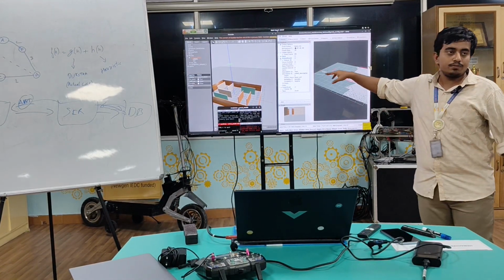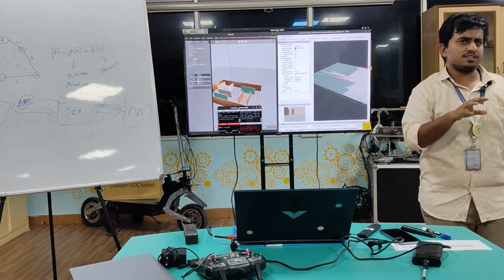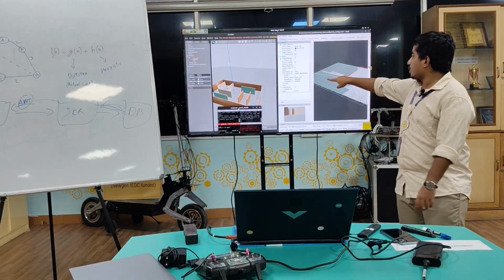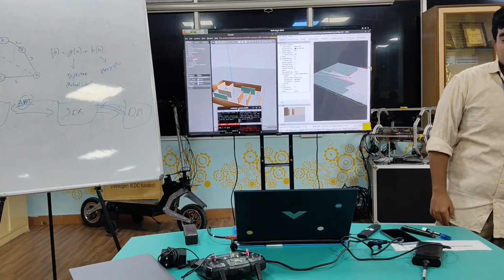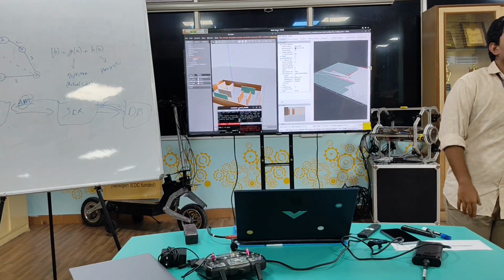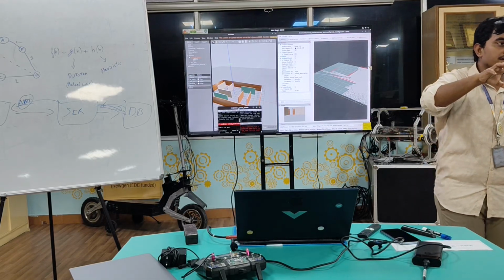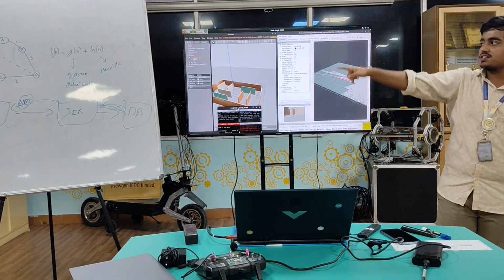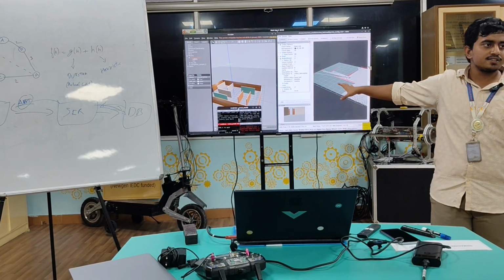When you run your system all around the environment, the whole environment is mapped, and you can use certain files and commands where you can click here. If your bot is here, the bot will navigate to this place. There are some conflicts happening, so I couldn't run it as of now, but that's how SLAM works. And you can ask me, when I click here, how is it finding the shortest path, right? There are multiple ways it can reach this point. For that we are using the A star algorithm. So this is the basics of ROS.